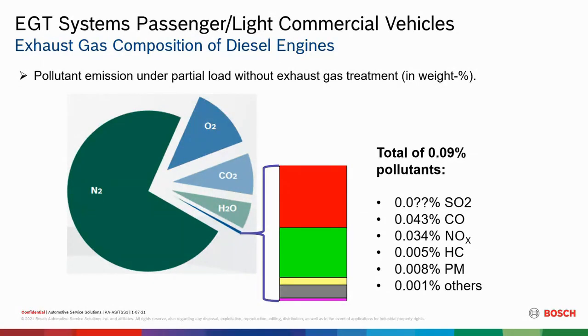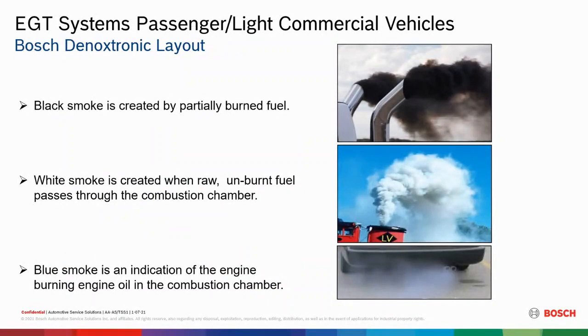because we'll damage that. Now, in the past, years before electronic diesel, before this aftertreatment system, a diesel would pull in front of the shop and we could just look at it idling outside or even run down the road and we could just get an idea of what's going on. So this first one, the black smoke, is that partially burned fuel or CO that's pumping out the exhaust. And we still see this today with people that put performance kits on. And if that aftertreatment system gets contaminated badly, you can still see it again. But it's a very rare thing that we see this anymore.